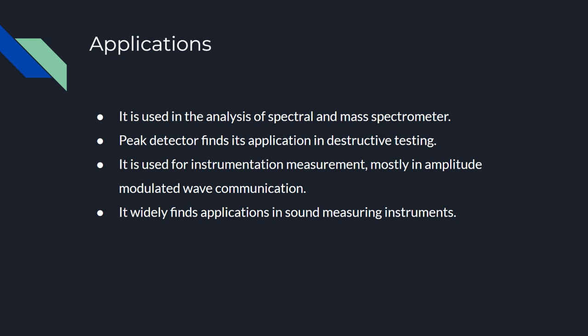We consider these three components for an op-amp performance because the reference voltage determines the threshold at which the peak detector starts to detect the peak value. The load resistor and the storage capacitor determine the speed and stability of the peak detector. Hence, by taking care of these mentioned components, we can adjust the performance of the op-amp to fit several applications.